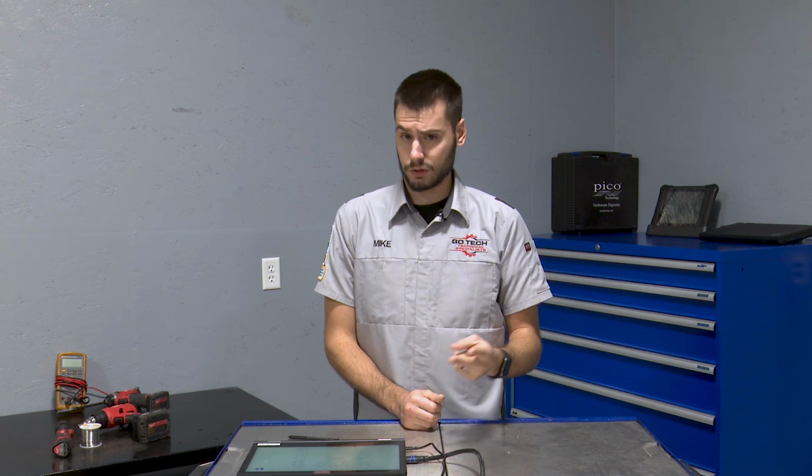Is it likely the radio fails at the same time the driver's power window switch fails at the same time the cluster fails? Probably not, right? And then for them to happen intermittently, when one comes back, they all come back. When one goes out, they all go out. There's likely something tying this all together.